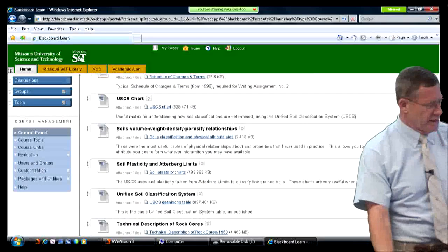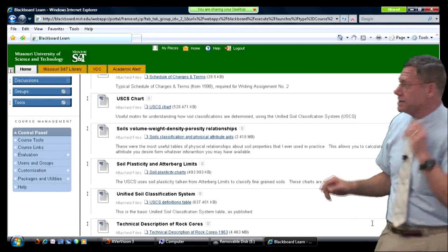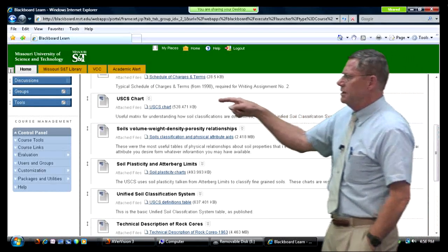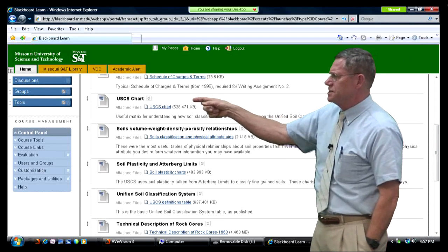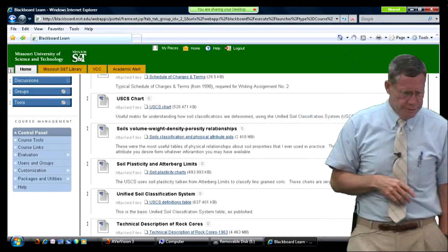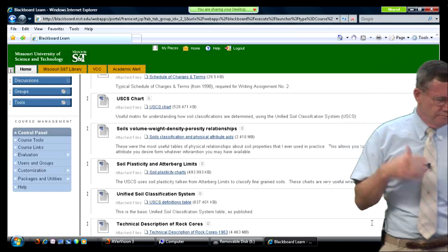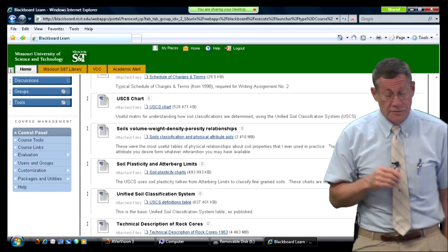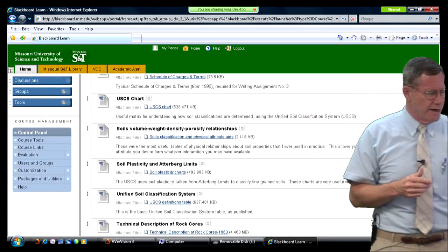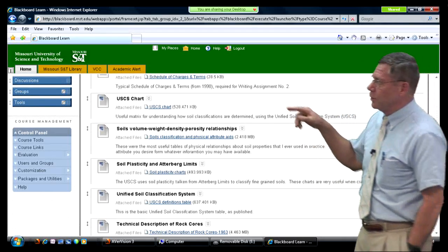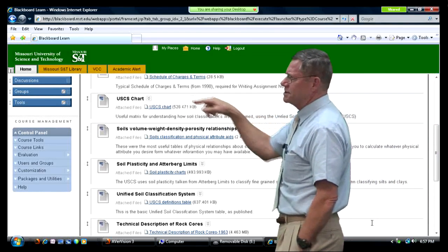This thing here now, we're going to get into the things that are soil mechanics oriented. And this is the USCS, Unified Soil Classification System, which is what most people use in the country. ASTM uses it. There are other systems out there that are even better, but a lot of people are not trained to use them. But we're going to use the Unified Soil Classification System.